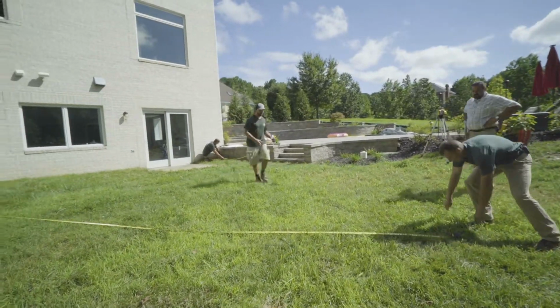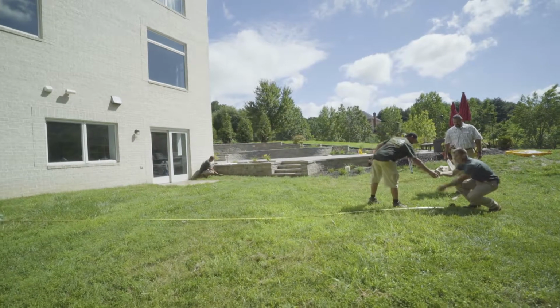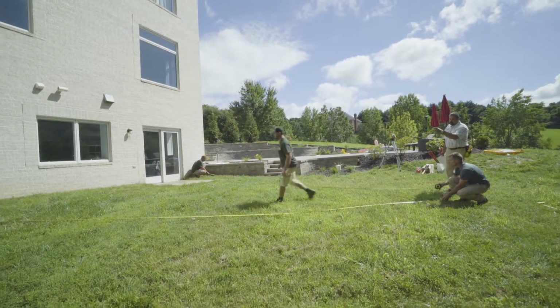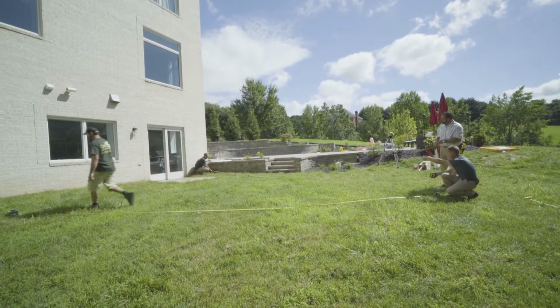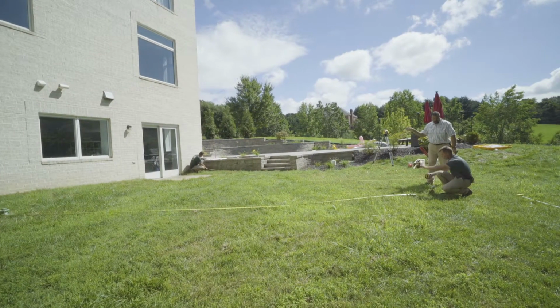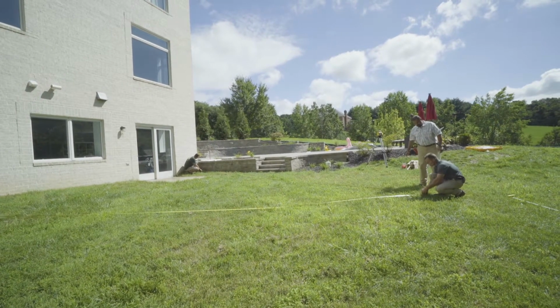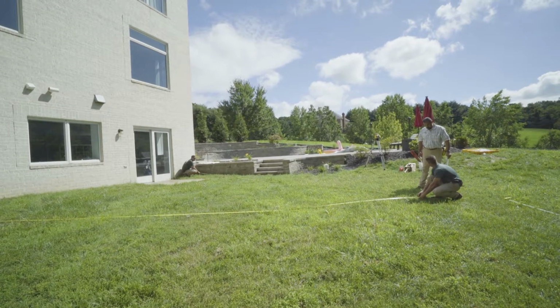So the way we did that, grab that and then go back and make sure you hold that point for me, please. So you're 32 off that corner of the house. And 30 feet off that corner of the fixed wall. So we have fixed points. So we cross our tape measures right there. There's 30 and 32, you see?